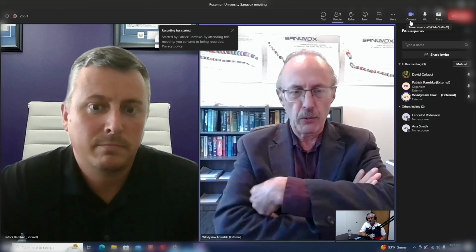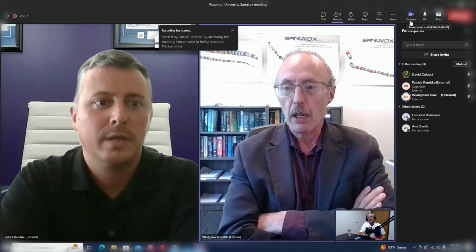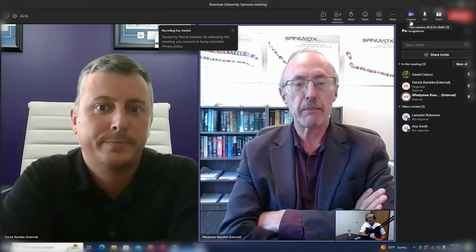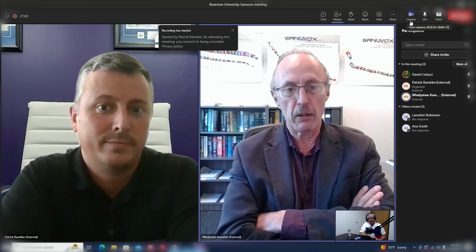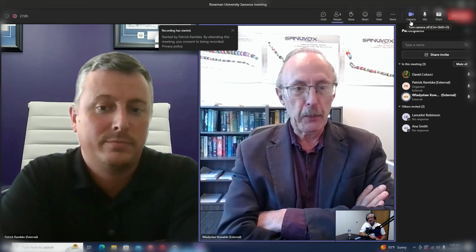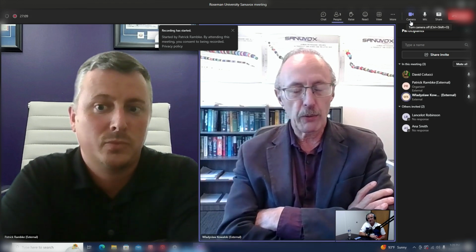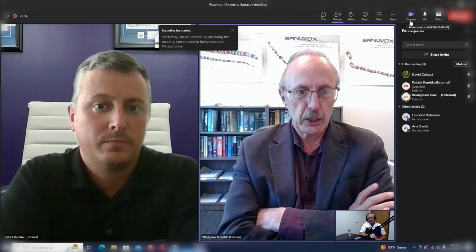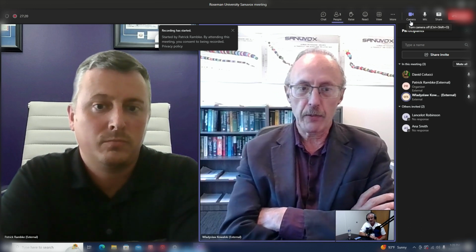Now, ASHRAE 241 is recommending something like 6 air changes per hour. Most buildings do not have that presently. They're lucky if they have 1 or 2 air changes per hour. Now, many people think they might be retrofitting their air handling units to increase the airflow from 1 or 2 ACH, air changes per hour, to 6 air changes per hour. They may quickly discover that that's a very expensive option.